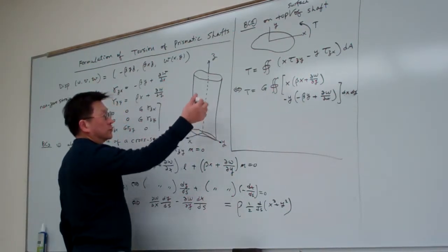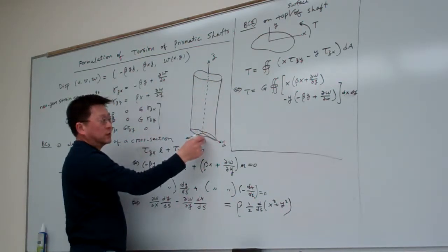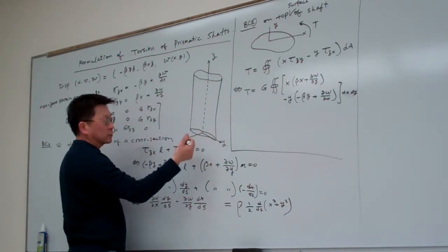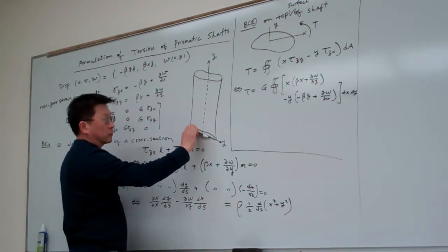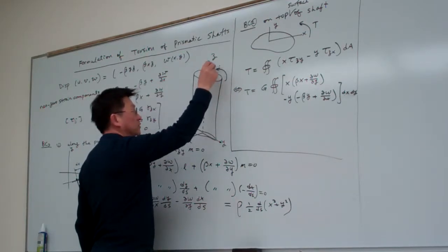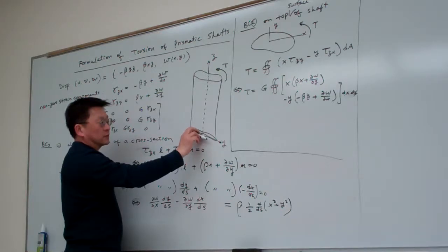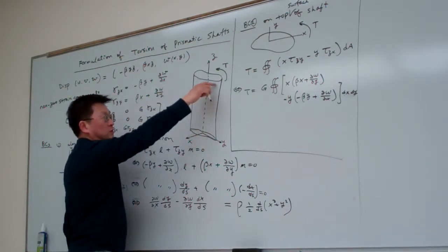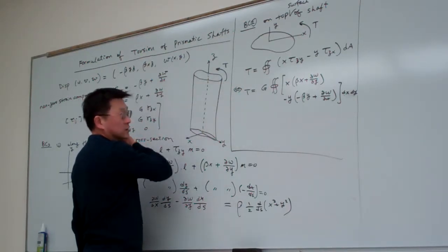A pure torsion is basically a couple of torsions applied at the two ends, or, for simplicity, you can assume the bottom face is fixed in all degrees of freedom, and only the top is under torsion. Usually this scenario, fixed at the bottom with a twist on only one side, is easier to comprehend. So here I put the torsion like this.